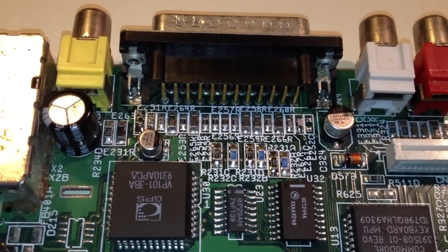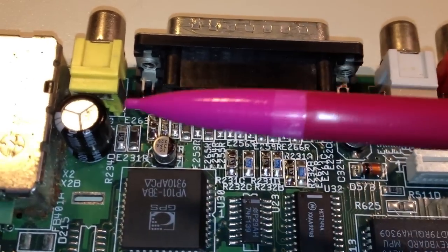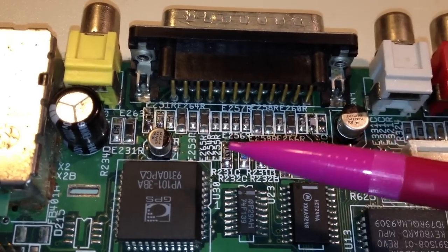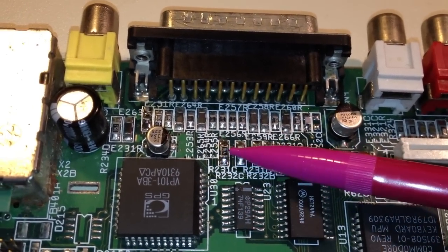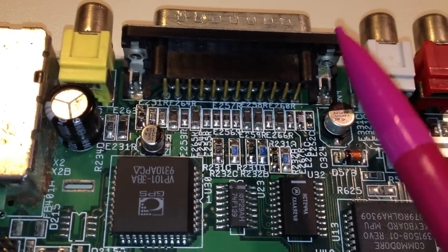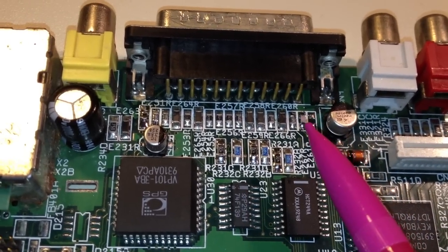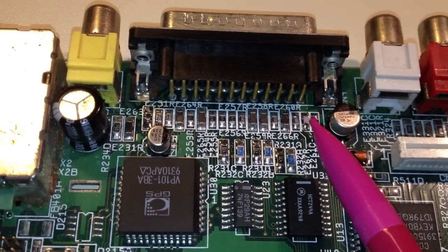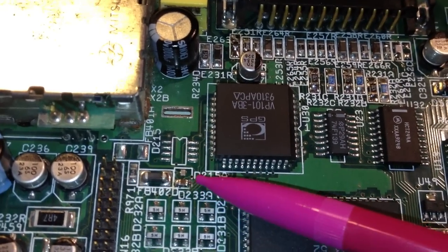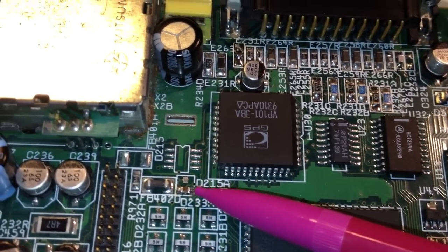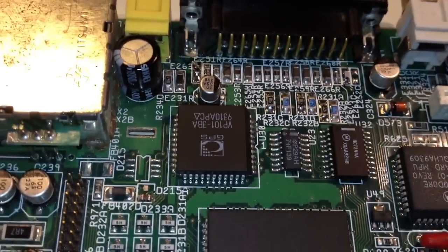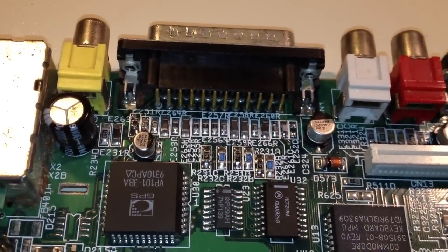Okay, so that's it. I'm done working on this motherboard. So just to summarize it, I desoldered a 9.8 kilo ohms resistor that was in there and put a ferrite bead in there instead. I resoldered these three resistors, this, and this, because they were kind of sloppy soldered into place there. I desoldered the 9.8 kilo ohms resistor that was in there and replaced it with a 100 picofarads cap. And I also put 50 or around 50 nanofarads cap in there. So yeah, and the board is working now again, and everything is back to normal. So I'm pretty much done working on this motherboard.